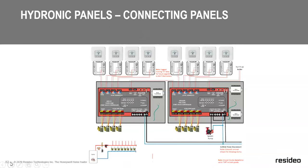We can twin them together if you're doing more, and if you have a more elaborate system, we also have our AQ zoning, which goes up to 64 zones. That also does what they call zone synchronization. So you're not cycling the boiler, it's anticipating a call from the zone and pushing the water out to that zone, anticipating it. So you get a flatter curve. You also pick up probably in larger homes 7 or 8% in savings, so you're not cycling the boiler on and off.